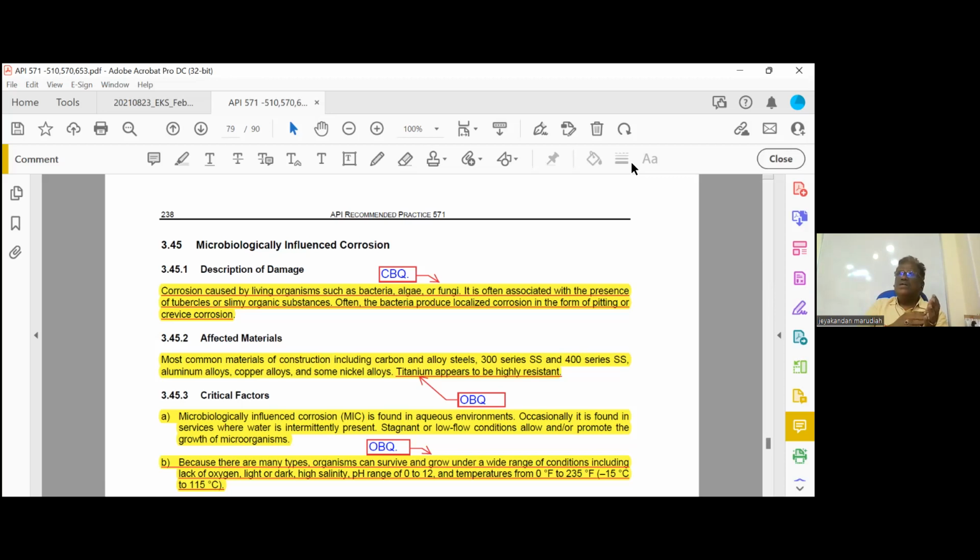Okay. NDT-wise, water analysis. You have to take a sample and check the microbe content. A bad smell of water indicates corrosion. If foul-smelling, bad-smelling water is coming, it means corrosion is happening inside. These are the key points.